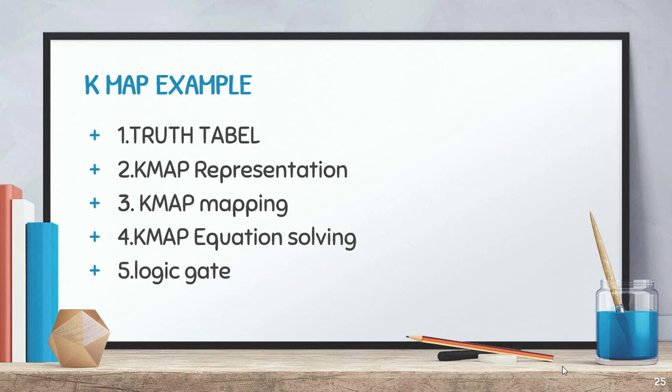Therefore, we can say that each product term implies the function and hence is an implicant of the function. All the implicants of a function can be determined using a K-map. From the above discussion, we can outline a generalized procedure to simplify a Boolean expression as follows.